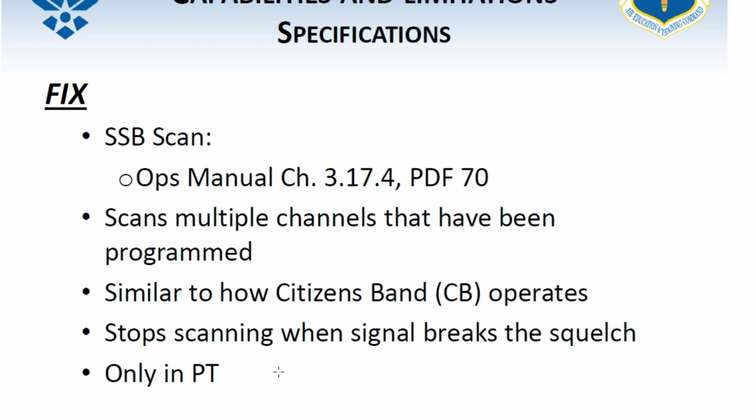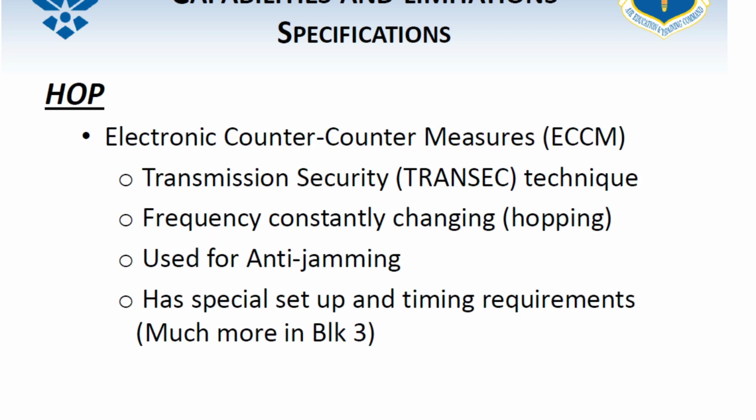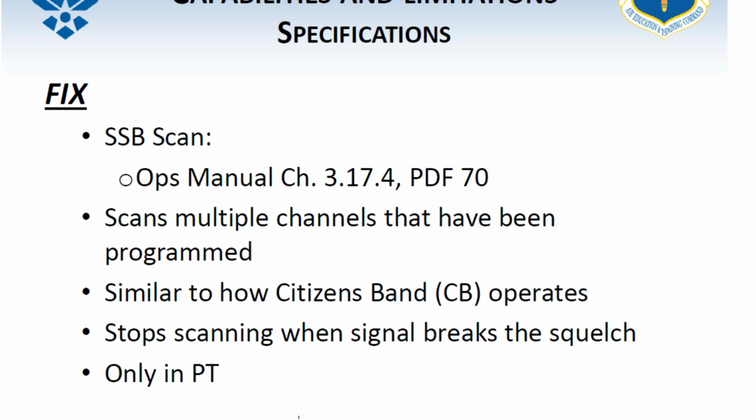What does plain text mean? Well, sir, right now we are talking in plain text. It is clear information. How do I get encryptions on there? You get those encryptions with a loading device through the accessory port on the radio. Through J6? Not the J18 fill port, you don't want to use that one. Let me look at my drawing for encryption.